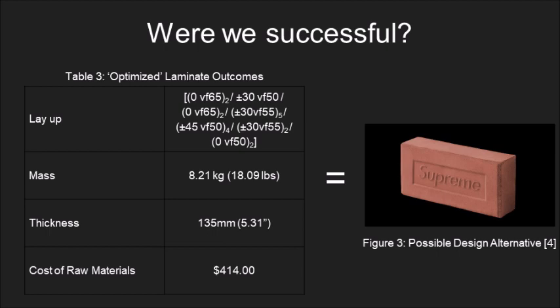Efforts were made to close the gap, and the final laminate does this better than most, but any efforts to make the CTE positive, let alone close to aluminum, caused the entire structure to fail under the necessary loads. We therefore elected to first ensure the laminate met the required minimum load scale factor, and then worry about the CTE, and our final design reflects this.